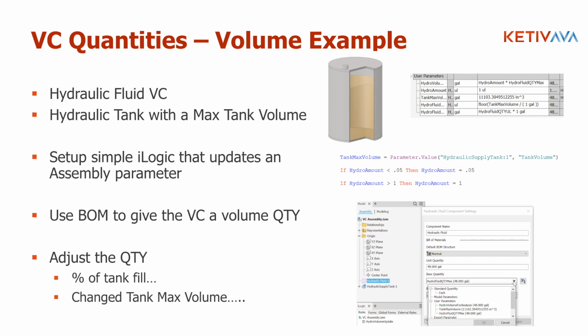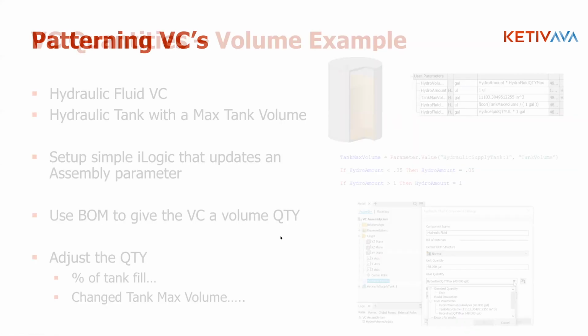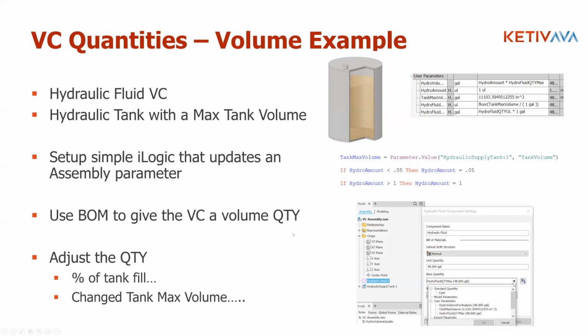And I've seen people online who have done that as one of the ways to create the reuse model, quote unquote. All right. And then I'm not sure if we got to Tim's question, but as far as being a child for multiple assemblies, if I'm reading that right, it sounds like you'd have to have that blank part that we were just talking about. You wouldn't be able to use a virtual component. Yeah, exactly. Virtual components don't have their own files, so they can't be children of other files.